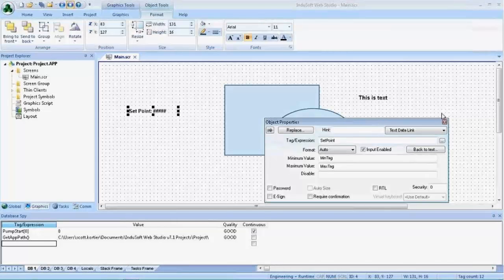And we did this concept where we put tag names in the minimum and maximum values, and we could choose these tags to be entered on a configuration screen, or in their case, they actually chose the values came from the PLC. So the PLC program dictated the minimum and maximum.